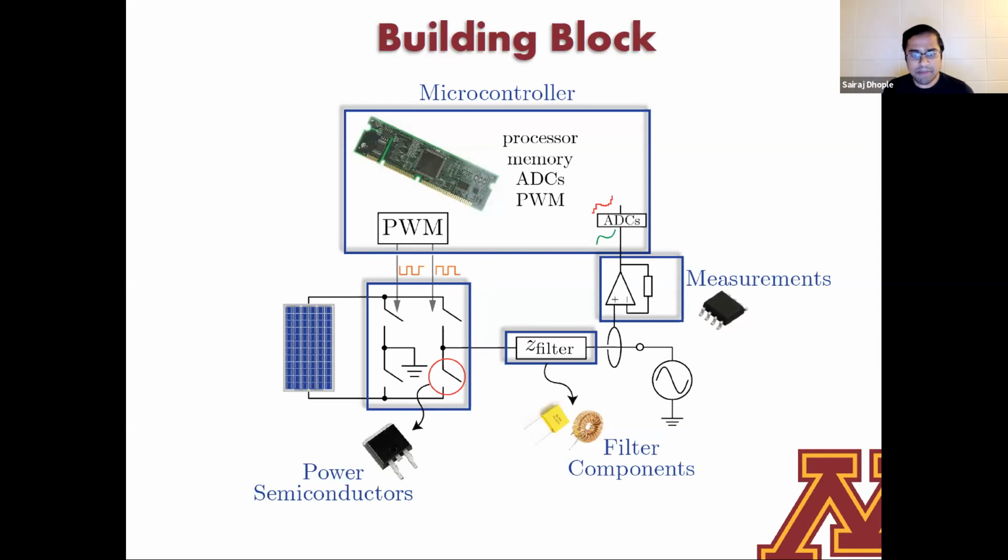And I'm going to make some measurements, in this case shown to be currents, it could be voltages at that point of coupling, process that through a microcontroller, which is going to implement my control code, and then close the loop with a pulse width modulation switching scheme. All that I'm going to talk about today is intelligence that lies within this microcontroller. So I'm going to talk about control strategies that can be implemented in order to give you some desirable properties from system as well as individual inverter level points of view, and we'll see what that's all about.